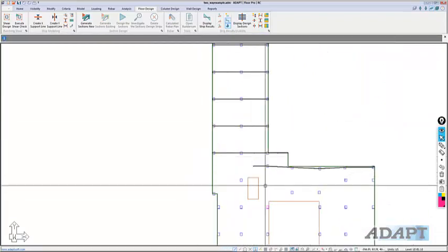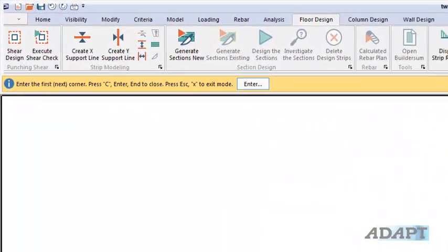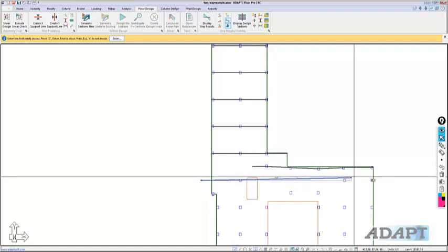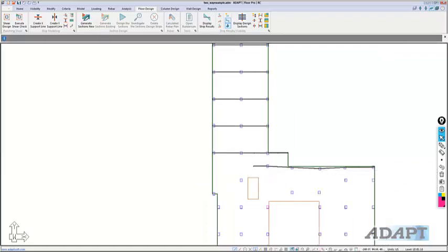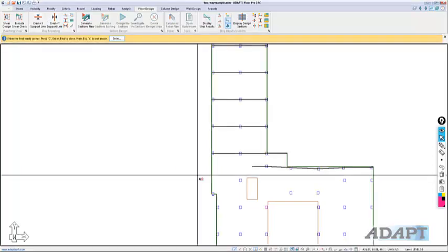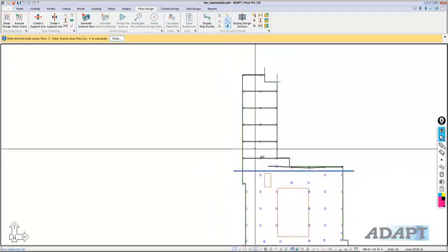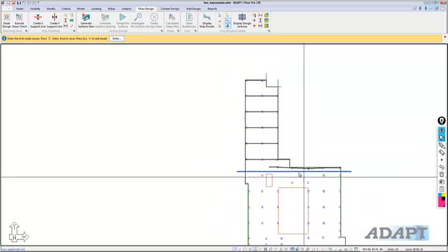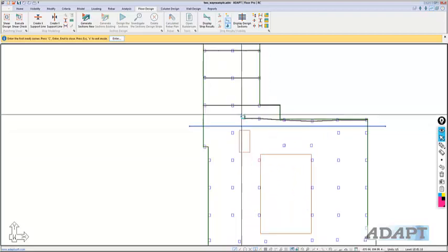Okay, here we need to create a boundary, so we're going to create what's called a splitter, X direction splitter. The first splitter I'm just going to place straight across here. Let me try that again. I'll put a splitter there, and that bounds off this wing from down here. So in other words, the strips can't extend below that splitter.